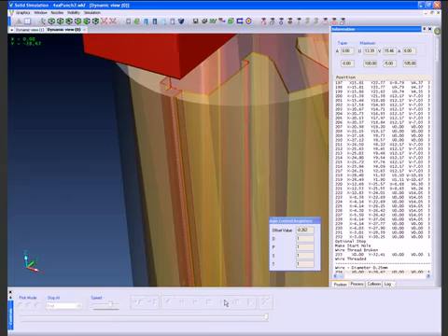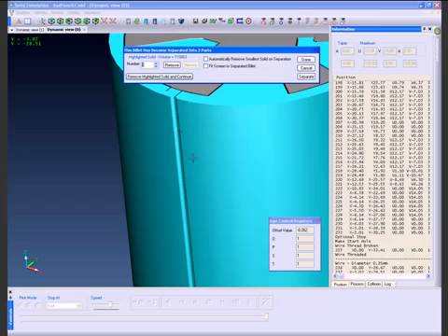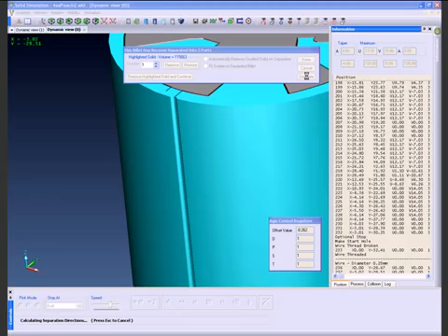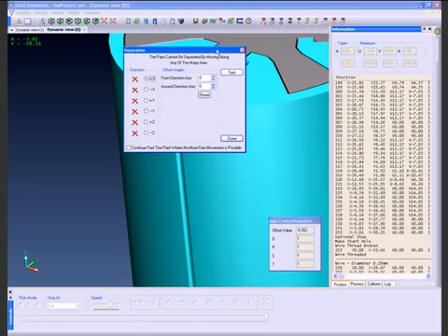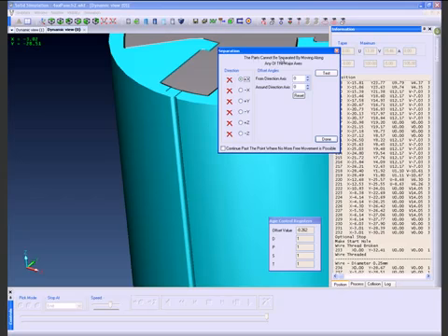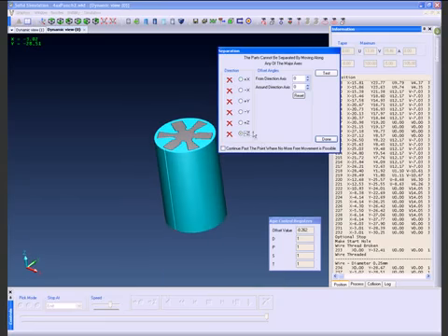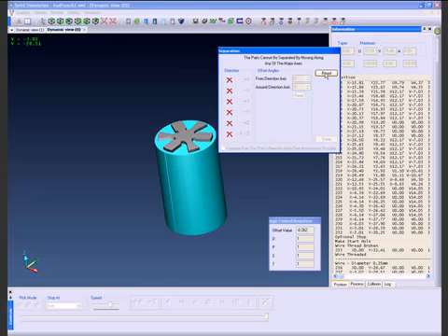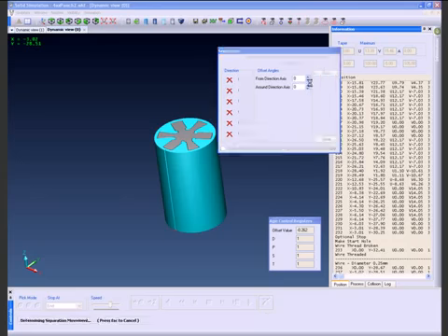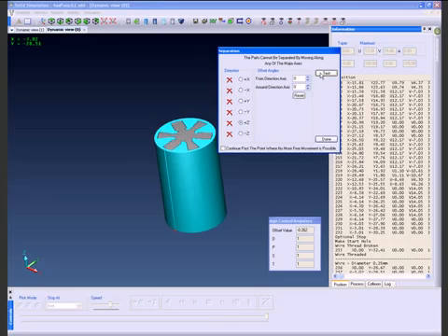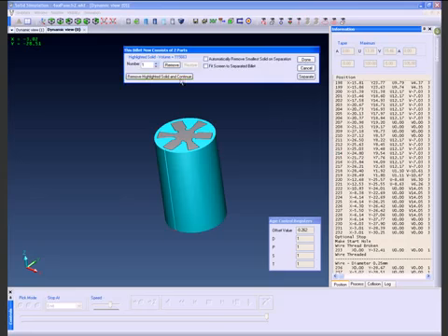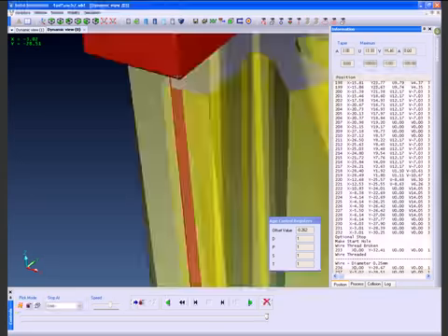Having completed the simulation of the wire path, we can now move on to the separation dialog, which will indicate graphically whether the part can be removed safely from either the Z positive or negative directions. As you can see from the crosses in the dialog, it's already indicated to you this is not possible, but if we do it graphically, it physically shows that it cannot be removed. If you want to override this, you can, and continue with the end of the simulation to show the single cut for the tag at the end.